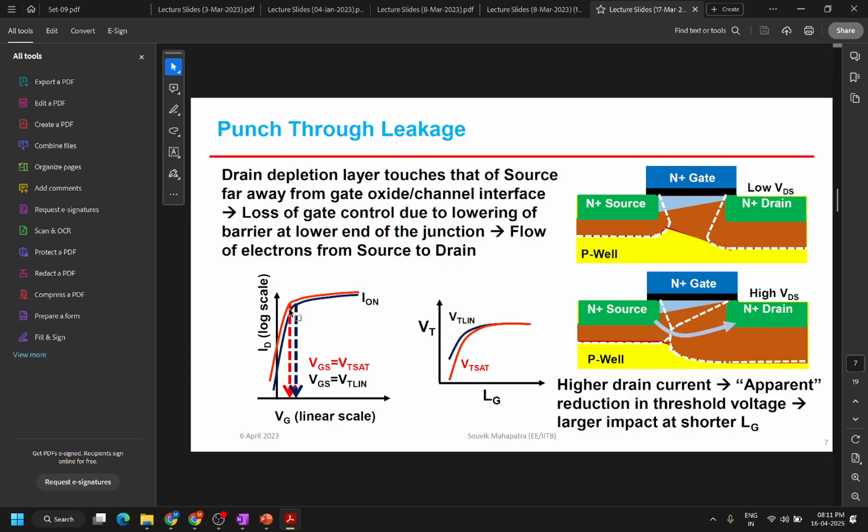But sir, in off time, their leakage current will be high. In that case also, yes, that is causing your leakage because the channel is now left shifted. So it can only go a maximum of 60 millivolts per decade, right? At threshold.